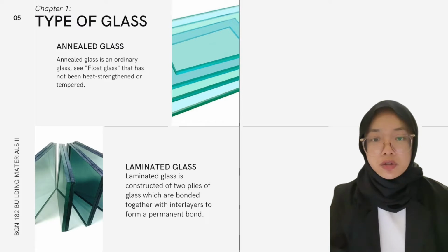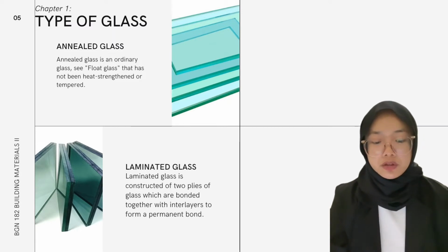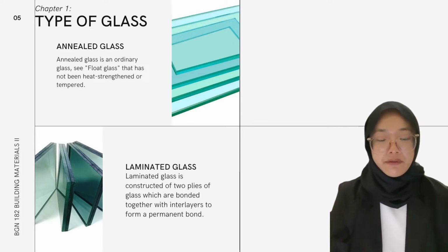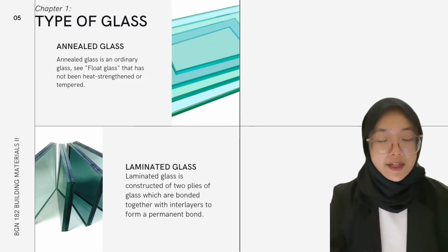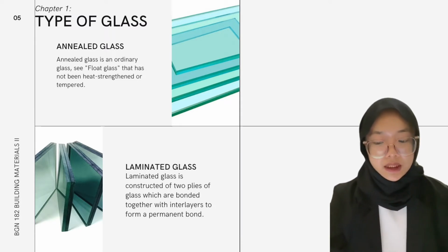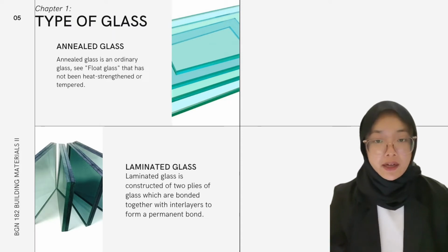This glass also consists of a layer of plastic known as PVB. It's located between two sheets of float glass. This layer of plastic, when we use in glass manufacturing process, bonds the glass together so that if it breaks on impact, the shards remain together instead of shattering. This is why laminated glass is used in places where there is a possibility of injury during an accident.